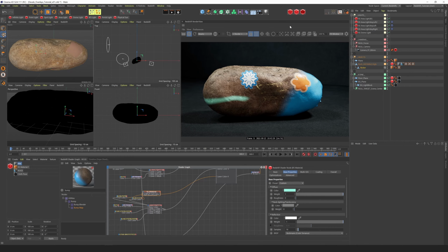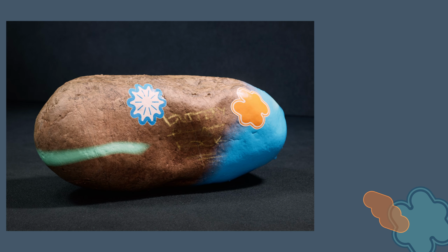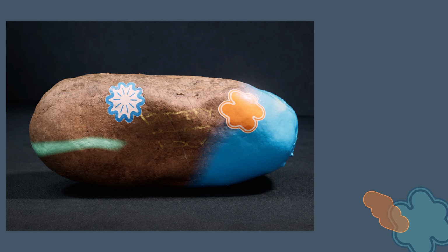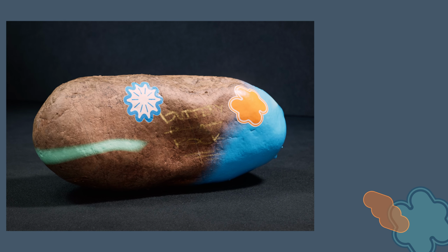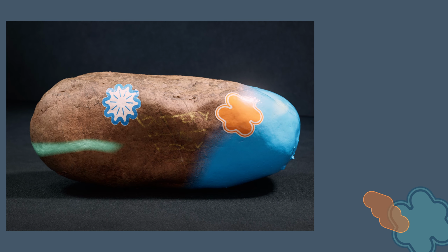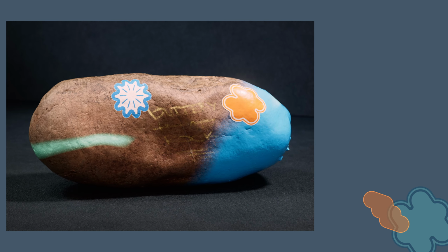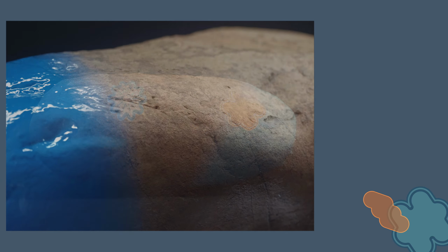All right, I think that pretty much wraps it up. It's basically the same sort of ideas either way. If you're applying a sticker or some writing, it would just be setting the UVs for that specific item that you wanted and then masking out the projection from the opposite side. And, you know, I showed here the ramp and UV projection node to do that.